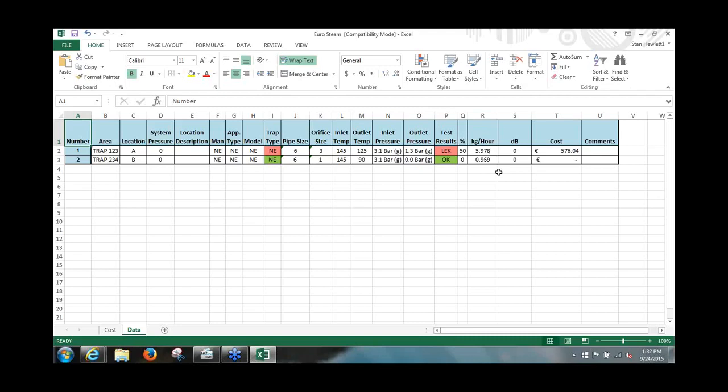Any other questions? Perfect. Yeah, one other question here. I'm sure this was just an oversight, Stan, but the question was, noticed that you had on your report the Ultraprobe set at 40 kilohertz, and he was asking whether it should be 25. Yeah, we always say anywhere between 20 and 25 kilohertz to actually listen to a trap.